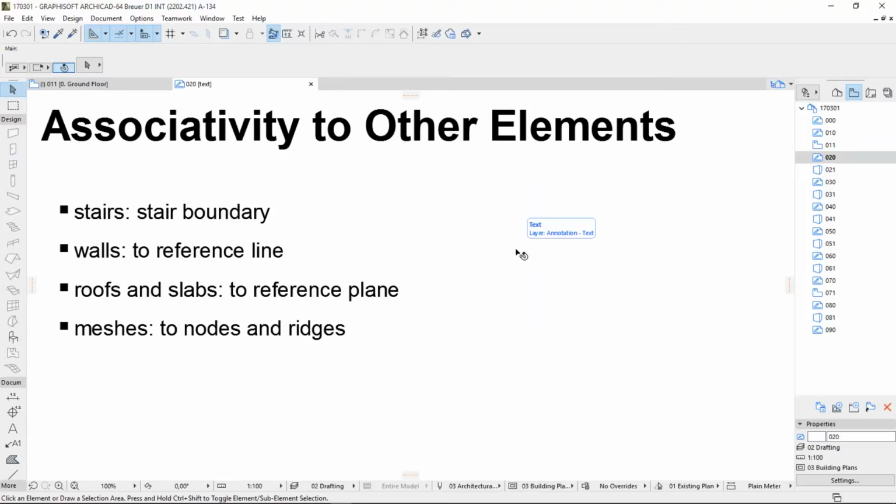That's very important, so that we can attach railings to stairs. We can attach railings to walls, which can be a very useful case when you have a railing that runs along the stair. Then it goes up to, I don't know, another wall, and so on the stair it has all the components in it, but on the wall, for example, it's just a top rail, and it runs along the wall.